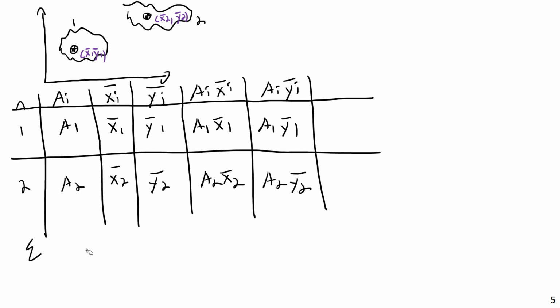Then I would sum these up. Well, actually, I could just call that A, the total area. The summation of A_i x bar i is basically going to be your Q_y, the first moment of area with respect to the y-axis. And so then the summation of the A_i y bar i is basically the Q_x, the first moment of area with respect to the x-axis. And then the overall combined x bar is just going to be the summation of all the individual A_i x bar i's divided by the area, or just the Q_y divided by the area.